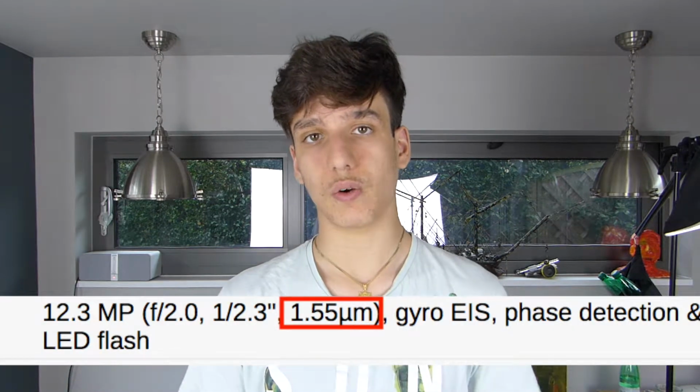You might see on the spec sheet, in the same section, 1.22 micrometers, or a similar number. All this means is the size of each pixel within the camera sensor. A pixel within a camera sensor is what actually absorbs the light, so basically sees the image, if you will. And the larger each pixel, the more photons, so the more light it can capture. So that's all that's referring to, the size of each pixel within the camera sensor.